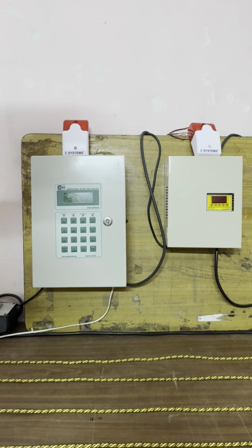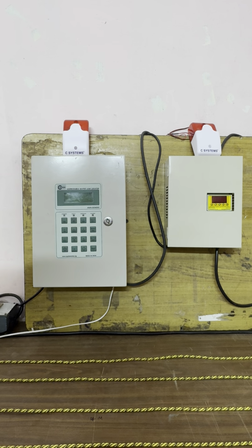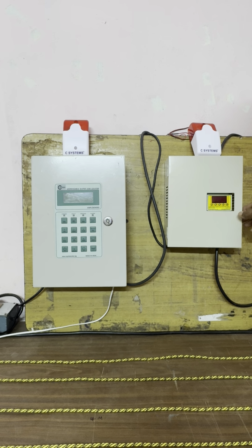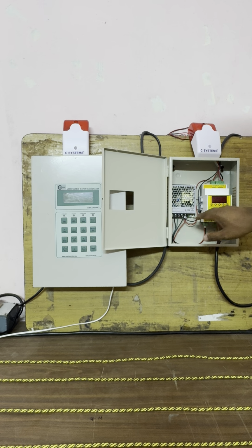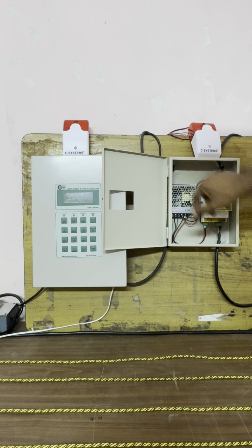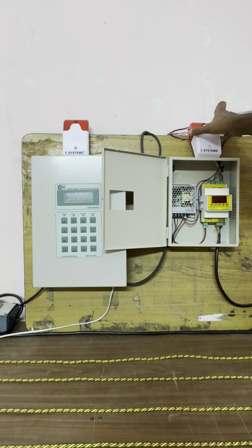Now we will come to the module explanation. The module has an inbuilt power supply, a 12 volt 3 amp power supply. We have connected a 12 volt supply directly to this, and the sensor cable is connected to the 4-pin terminal, which is embedded along with the sensor cable. The communication cable has a 5-pin connector where D plus and D minus are connected to the master panel, and from this module to the next slave we have to connect D plus and D minus for daisy chain topology. There is also wiring which we have done for the hooter output.